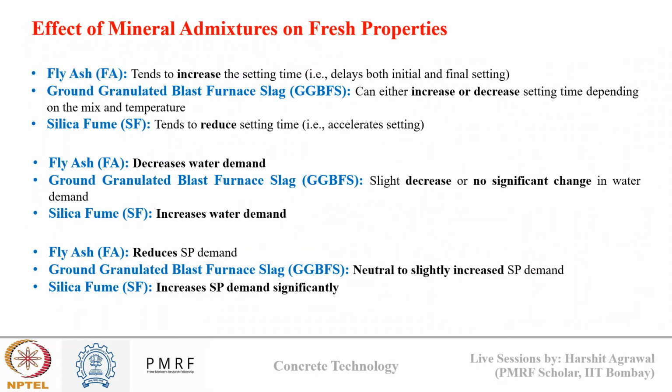We talked about the effect of mineral admixtures on fresh properties like setting time. We discussed that fly ash, due to its ball bearing effect, delays setting, while silica fume, due to its high surface area, accelerates the setting. The same reasoning applies for water demand and SP demand also, where fly ash will reduce water demand and SP demand, while silica fume will increase water and SP demand.